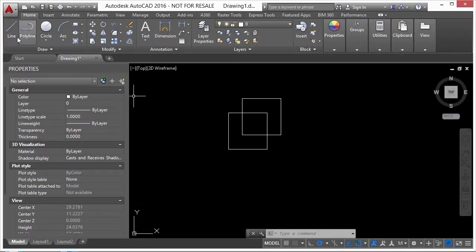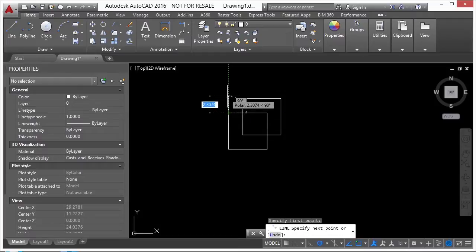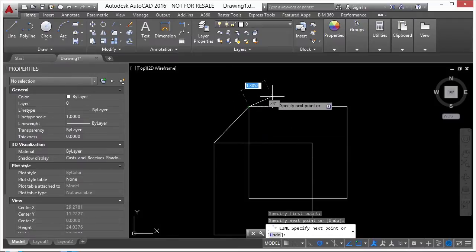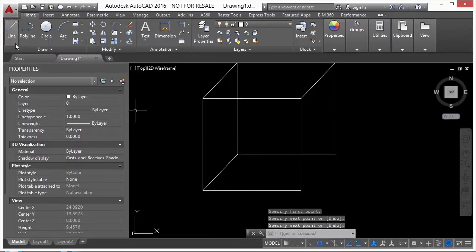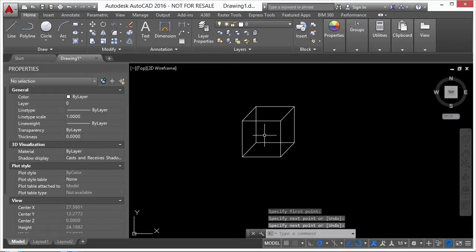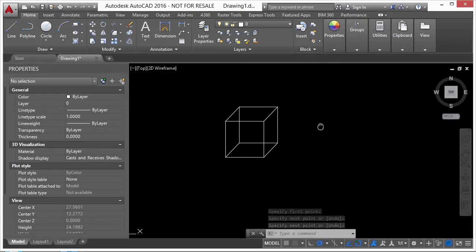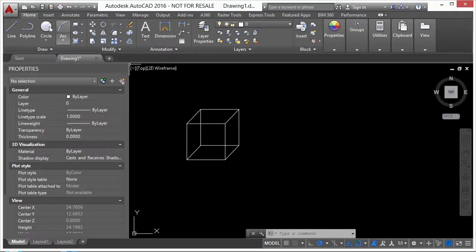So now I'm going to draw lines connecting all of these items here. So I go up to the line command. My O snaps are on, so that's good. That helps me save time. And I go there. Right click again, start the command again for the line. And there we go. See, nice and simple, not difficult to do, of course, but there was a lot of back and forth. So you see, I'm going back and forth and back and forth.